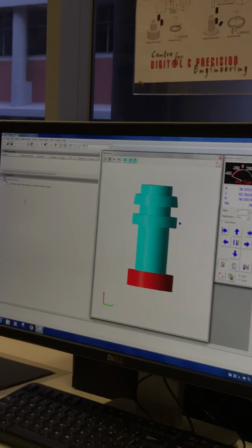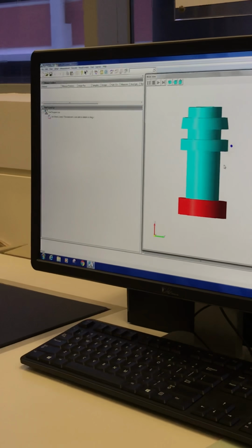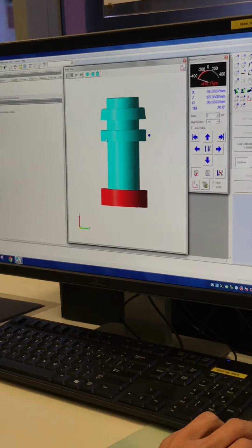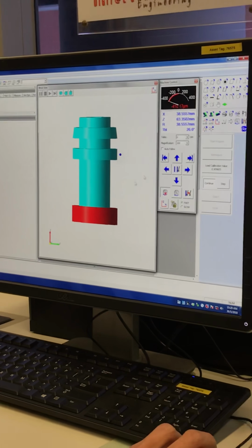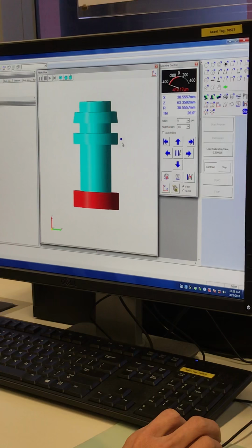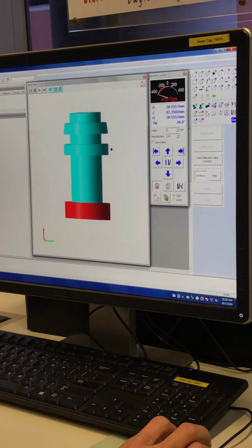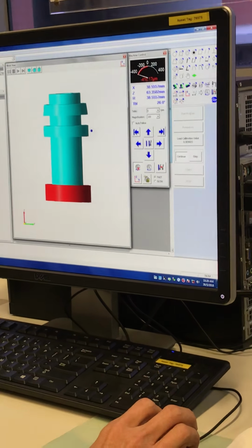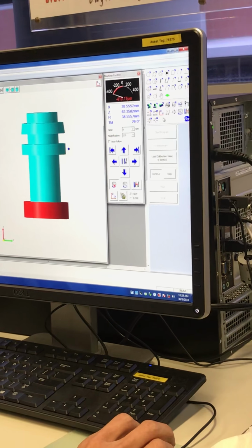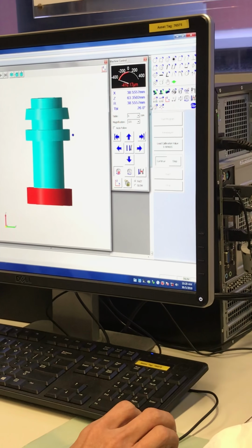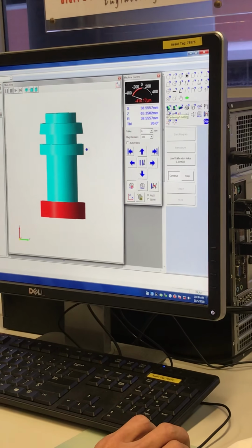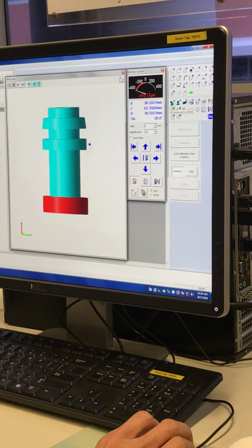This window here is the measure condition window. This one is the part programming window. This is the sensor as well as the CAD drawing, for you to see where the sensor is. This one is the machine control. Over here are all the commands, and over here is the setting command. The setting command that we are interested in is here, centering and leveling.